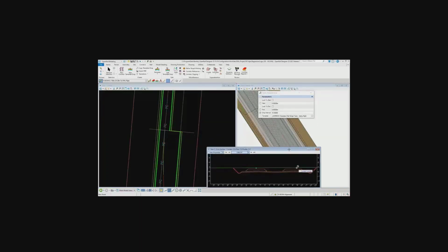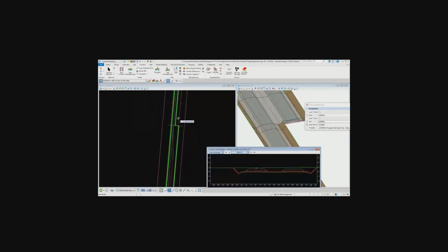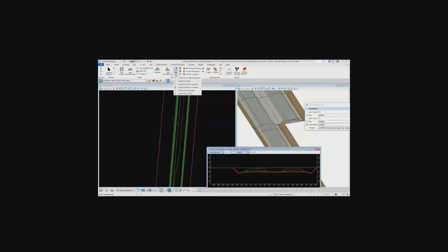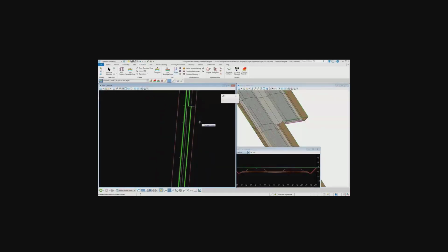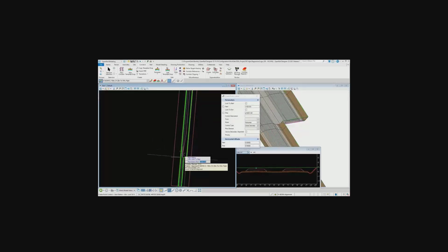Now, in this case, it's not anymore flat in the sense that the ballast is pretty much well defined, such that you will really see a difference between the main line, then it goes to a bit of a flat sub ballast, and then again a well defined ballast when it goes to the yard portion.